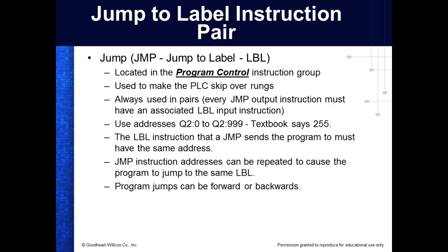We do this in PLCs. On a robot, the program does not loop until you make it loop. So you have to put a jump instruction at your last rung and send it back to a label, and it works the same. Jump instructions have been basically the same in every programming language I ever used. And sometimes in true computer programs, if you don't make it loop, it won't what? It won't loop. In PLCs, it automatically loops.